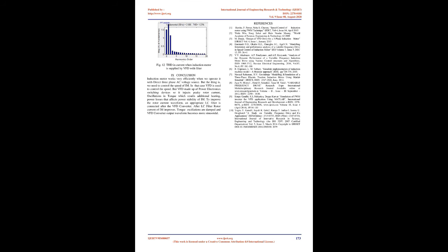8 Simulation and Results. In this simulation, the circuit models a 3-phase induction motor fed by a VFD system. The variable frequency drive system is made up of a PWM inverter. A 50 Hz voltage source feeds a 5 HP induction motor through an AC-DC-AC converter. The 600V, 50 Hz voltage obtained at the secondary of the Y/delta transformer is first rectified by a 6-pulse diode bridge. The filtered DC voltage is applied to an IGBT two-level inverter generating 50 Hz. The IGBT inverter uses pulse width modulation, PWM, at a 2 kHz carrier frequency. The circuit is discretized at a sample time of 2 us.